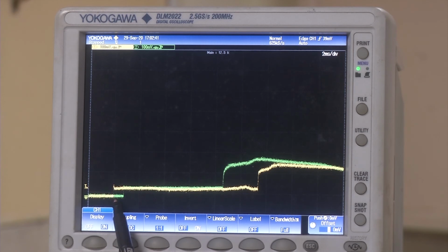Now, till that point of time, you can see that the green line, which is pressure transducer 2, doesn't see the shock wave. So, it is shown as the same reference line. Now, after that, when the shock wave reaches the location of the second pressure transducer, this also sees the primary shock.